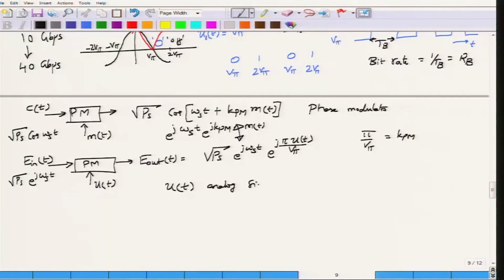For the case of sinusoidal phase modulation, you can take u of t to be some peak value uac cos of omega m t, and then you can see that the spectrum will have these Bessel functions, it will have sidebands which are infinite in number and so on.